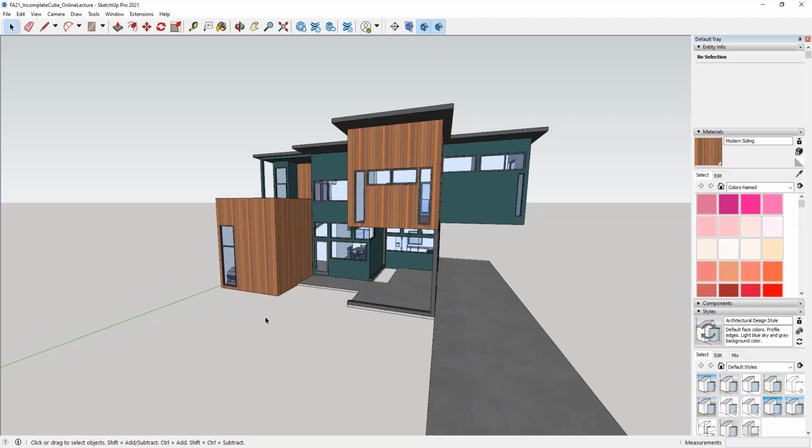Okay, in SketchUp Layout, it is simply a layout type tool. Think InDesign, maybe a little PowerPoint-esque in a way, but it really works well with SketchUp, and it allows us to take the views and the scenes, things that we've saved in SketchUp, and then apply them on a sheet of paper, which we can then dimension, annotate, and then eventually print and hand off to a client or a subcontractor, whoever it is that you need to pass this information on to.